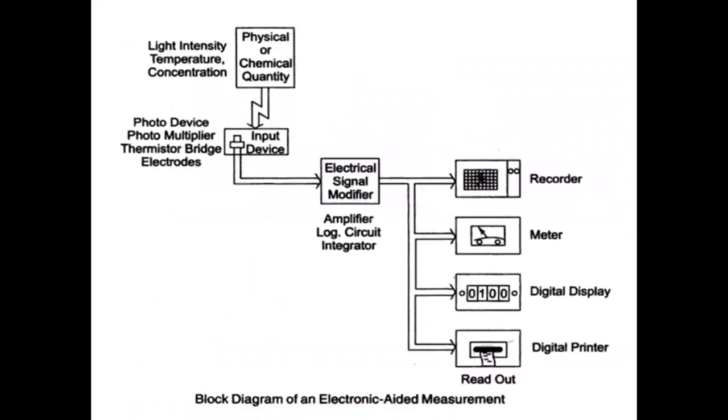Okay, so the physical quantity is converted to electrical, modified or amplified, and finally given to the output stage. This is the main thing. Now this is of two types: DC signal conditioning system and AC signal conditioning system. Anyway, the output is nothing but a number, and in order to have a digital format, again we have to go for the data acquisition system, where it converts the analog signal to the digital signal. So that is about the signal condition system.